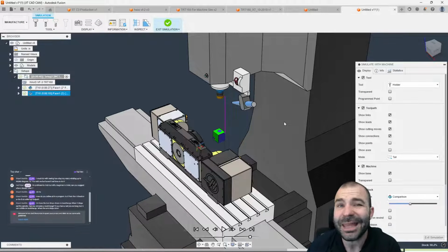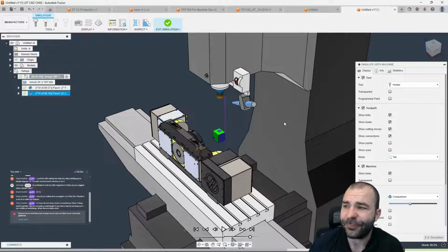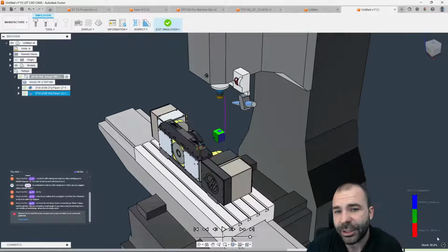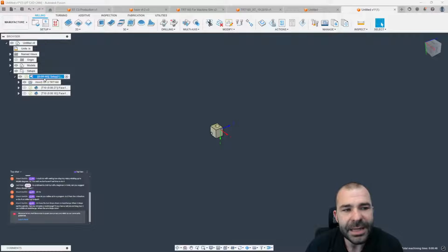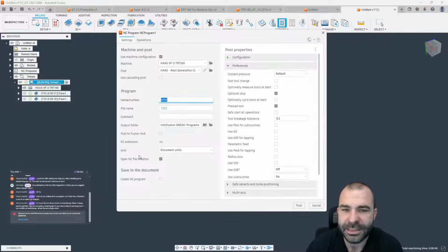But just like that, we've added our 4th and 5th axis, right? But let's take it one step further, as Stuart is calling, is we want to change where we go for tool changes. Now, that is going to be something that when we post-process, we're going to have to edit a post-processor for, which means I can't use the default post-processor.